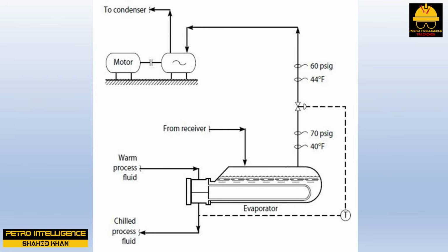For instance, suppose we are working with a reciprocating compressor. This particular machine has a very small volumetric clearance and a very high volumetric efficiency. These terms are explained in my lecture on reciprocating compressors. With this compressor, a significant decrease in discharge pressure will result in only a tiny increase in vapor flow. Therefore, the work or amp load on the driver will decrease.